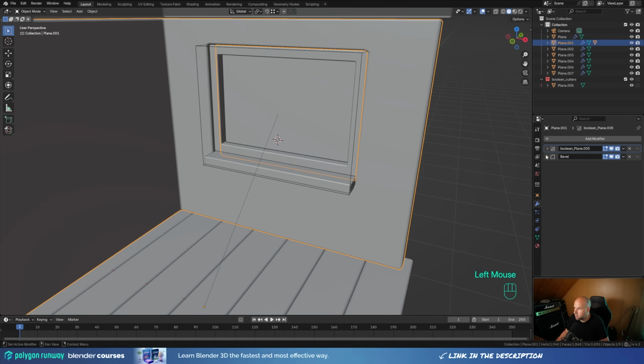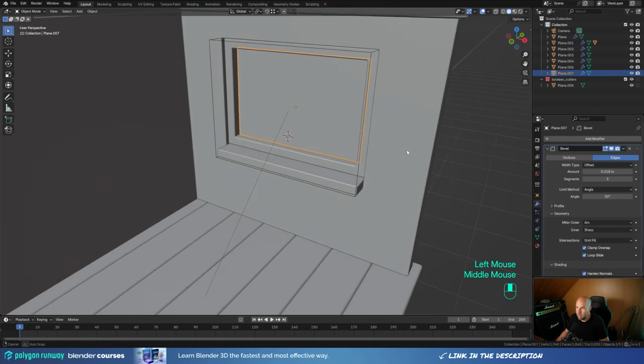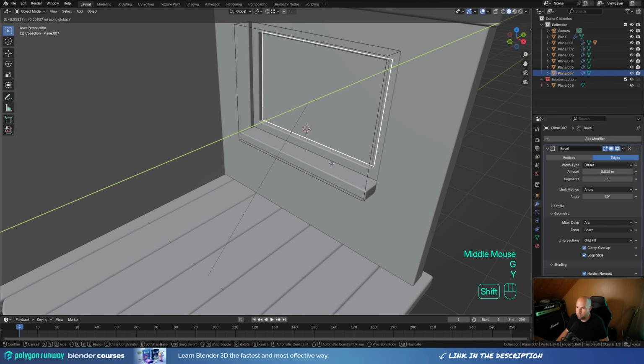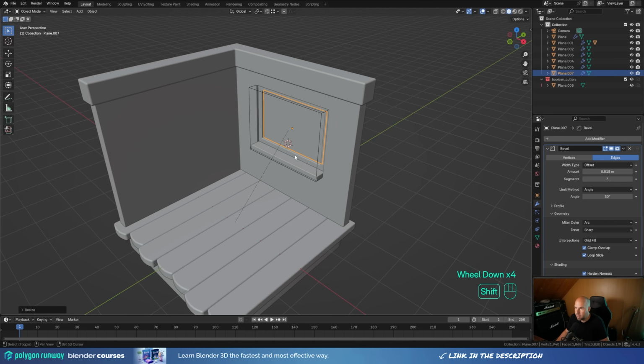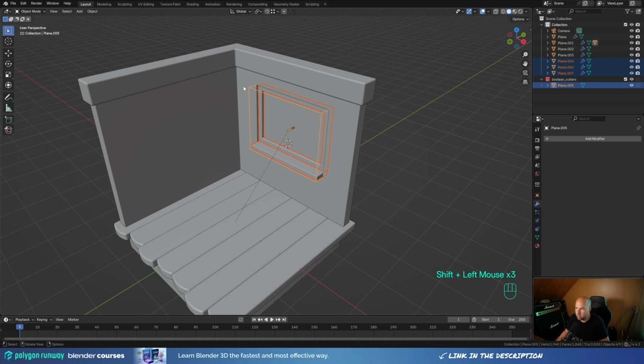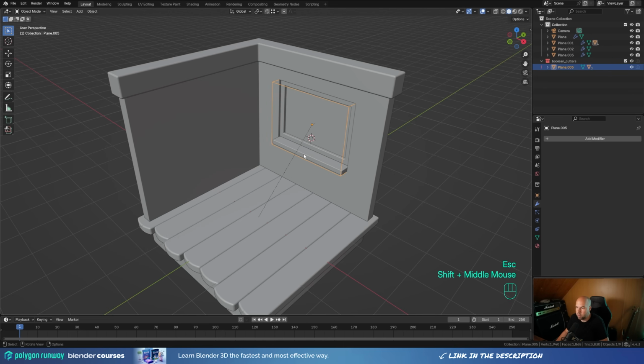Maybe we can adjust the bevel modifier on the wall here so it's not so strong like that. And now just select this plane, press G then Y and move it right here. Maybe we can make it a little bit larger so it better touches the window frame, but all in all this is okay. And now if we select all of these parts by holding Shift and select the boolean object cutter as last, press Ctrl P and parent to object, we can now, if we want, move the whole window with the opening, even scale it. So this is a very practical way how to create windows.